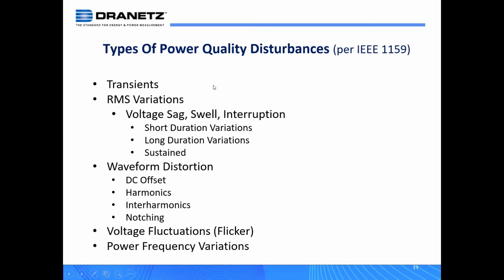So now to the meat and potatoes of this. Let's look at the types of power quality disturbances that we have. These are as per 1159, and these terms have been defined many years ago. And by the way, the one major thing that the IEEE is lacking is the overriding standard, like 61000-4-30, which has several substandards to define harmonics and flicker and other aspects to give you a well-rounded picture of a power quality measurement concern, where the IEEE has basically broken it down into substandards, but they don't have a top level standard.